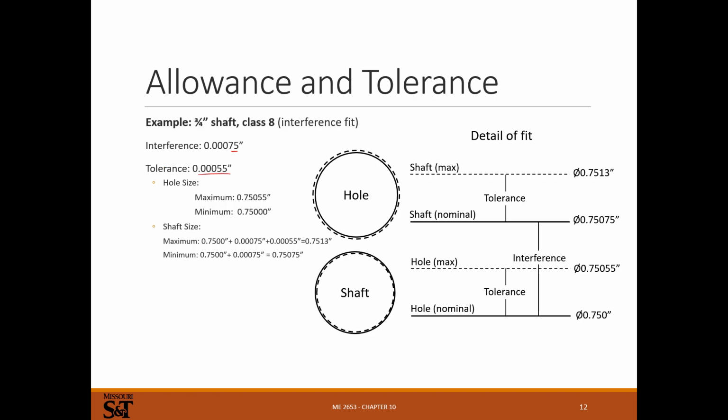Tolerance is also way down here. So there's not a lot of tolerance for press fits usually. Press fits, a little too much interference can cause problems. Not enough interference means it's not a press fit. So there's just not a lot of wiggle room on press fits. So in this case, what we need is the shaft to be bigger than the hole, so we have interference.